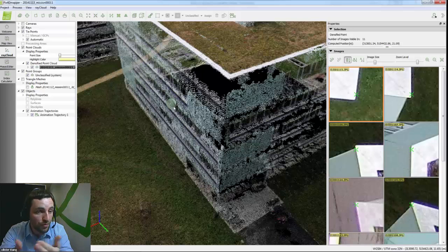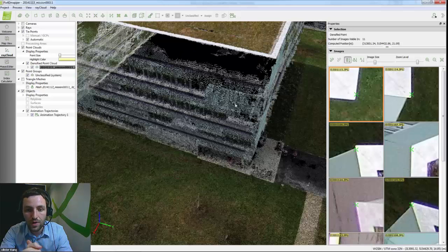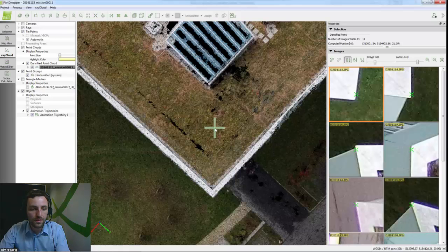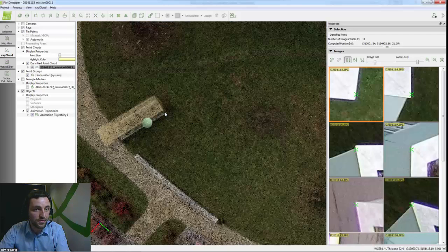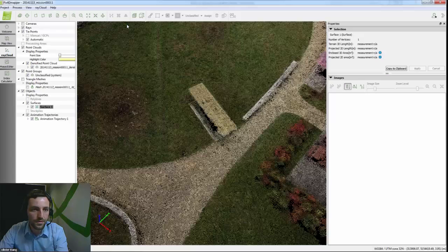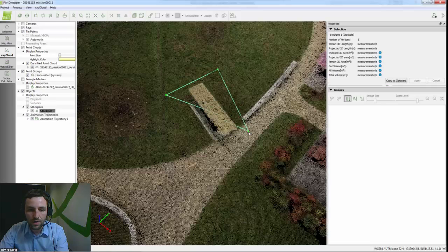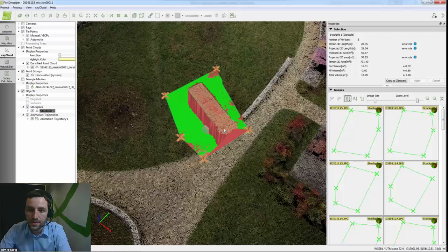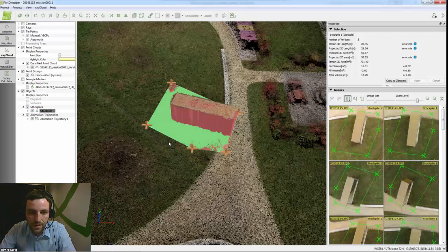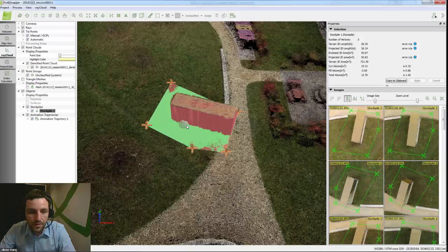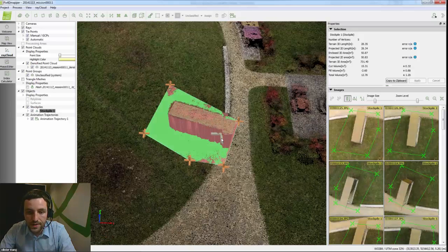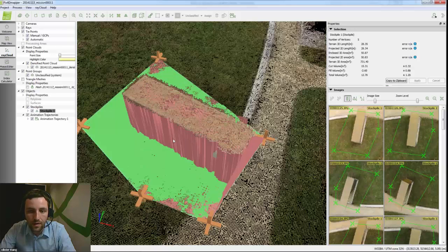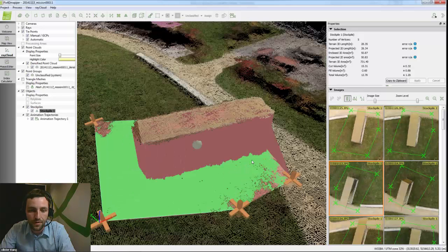Now, if you're using Pix4D Mapper Pro, you are able to actually output a lot more different formats of all the different possibilities. So one of them is the possibility to do volumetric measurements. So if you have Pix4D Mapper Pro, you can create a volumetric measurement, go around, for example, this area, and by clicking on it, you can then directly compute that you have 12.7 cubic meters in this area. Thanks to the very, very high precision that we have, this measurement is extremely accurate, and you can be sure that you are within a few percentage of the real truth.